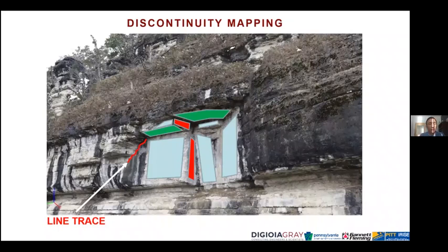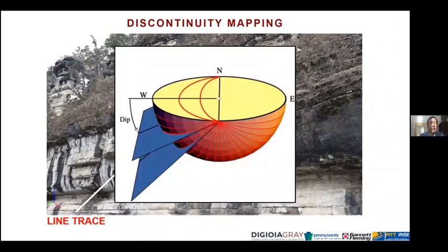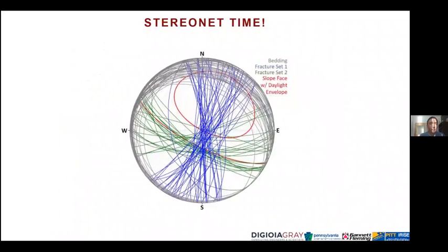And since this is a georeferenced point cloud, the planes are also correctly oriented in space. So once you've exhaustively gone through your digital outcrop and picked the planes and traces and all the features you want to represent in your kinematic analysis, you bring in your STEREONETs, your stereographic space.